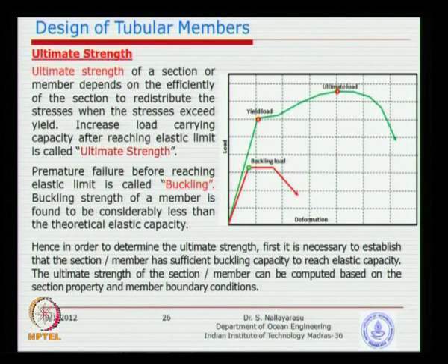So after buying a high strength steel and making the column 1 meter diameter, we are not even achieving 10% of the capacity, which is after all no good. So we need to proportion in such a way that you slowly march to avoid local buckling, avoid global buckling, then go into yielding. But at the same time, if you make it too big, too heavy, it is a problem for offshore structures, because it carries too much wave load, isn't it? Too heavy, no buoyancy is available, you can't install the jacket.